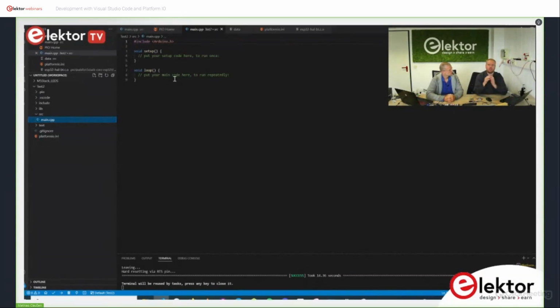The INI tells certain properties of your project. So the INI is a configuration file. And in this ini file, you can also have multiple configurations for one board, which is really interesting. If you, for example, would like to use another CPU frequency in the first place.